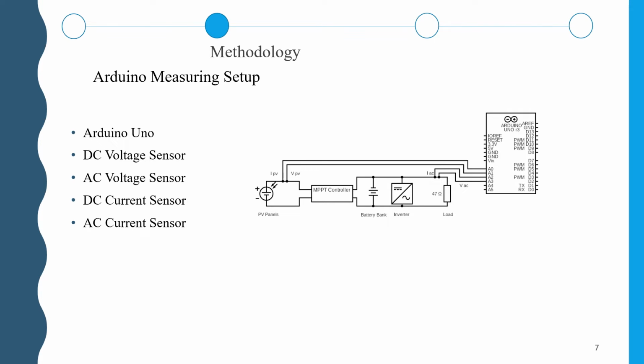A magnetic field is created when an applied current passes through the copper conduction path. This magnetic field is sensed by an integrated Hall IC, which then converts it into a proportional voltage from which the Arduino can calculate the current. The DC bus side is measured from the PV panels, while the AC bus side is measured from the output terminals of the inverter.